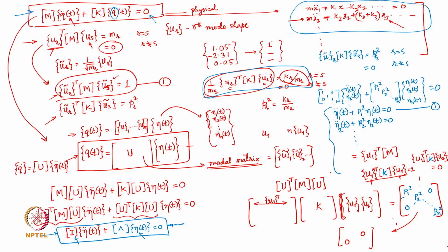You have been wondering as to why we are doing all of this, right? Why we are writing this kind of equations where the orthogonality was discussed, why we are transforming from physical to modal coordinates. All of that makes sense the moment you see the final result here, which shows all your coupled differential equations, n number of such equations. Suddenly you see that they are all getting converted into n single degree of freedom system equations of motion, which are quite similar to a single degree of freedom system.